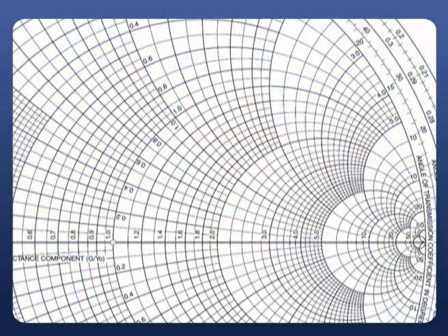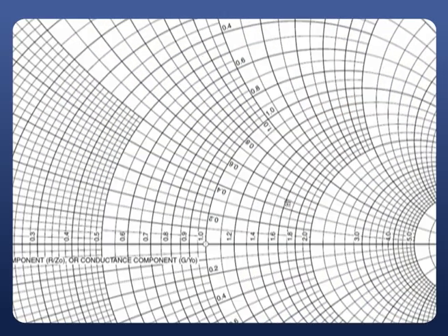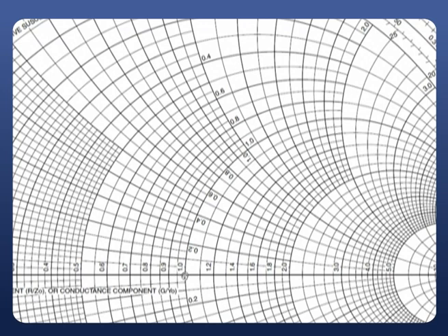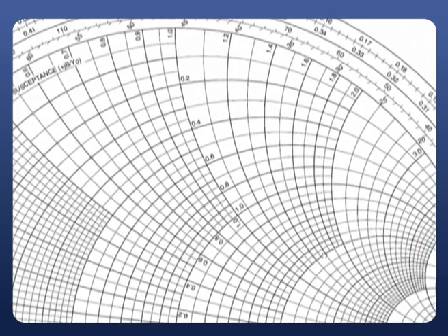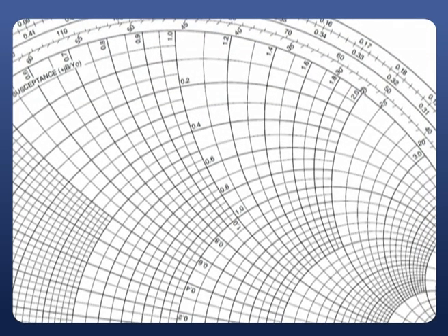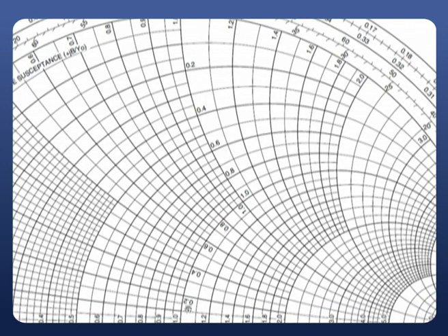Once again, I will try to represent those two circles on our Smith chart. Just observe here, on this Smith chart, the resistance circle for 1 is this circle, that I completely highlight. Now similarly, the reactance circle for 2 is this circle, right? So the intersection point of R is equals to 1 circle and X is equals to 2 circle is this one. It's exactly where the pointer locates the input impedance of 50 plus J100 ohms, right?